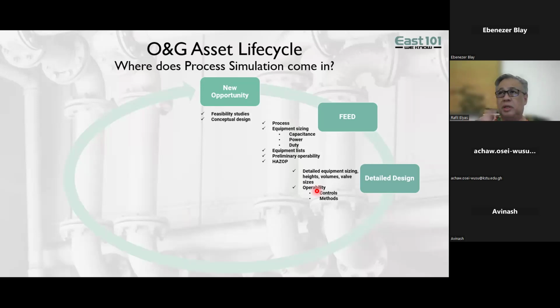I want to ensure that once I've commissioned, if I want to commission the facility, I want to come up with maybe a commissioning strategy or a startup strategy. That's when you start looking at dynamic simulation. Yeah. Sometimes you might want to start training your operators. Then you might want to take a look at some dynamic simulations which are coupled into operator training systems. Yeah.